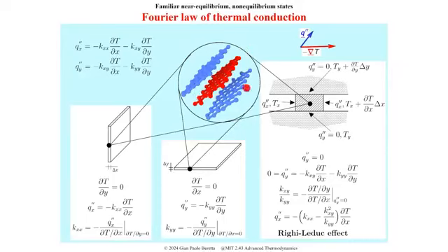And since those layers are inclined, as hinted by these inclined lines here, the heat flux enters here, but it likes to go up following the high conductivity materials. So that's why you build up temperature gradient in the direction where there is no net heat flux.